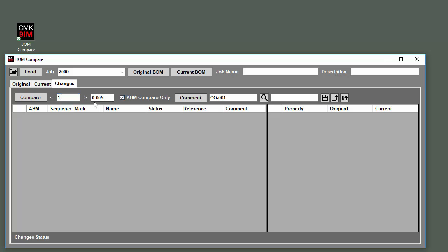If you choose this, it's going to only compare that and use this length underrun and overrun. If you don't, then it's going to do a detailed comparison and it will consider location and elevation in those grid references as part of the changes here. So let's go ahead and take a look at that.